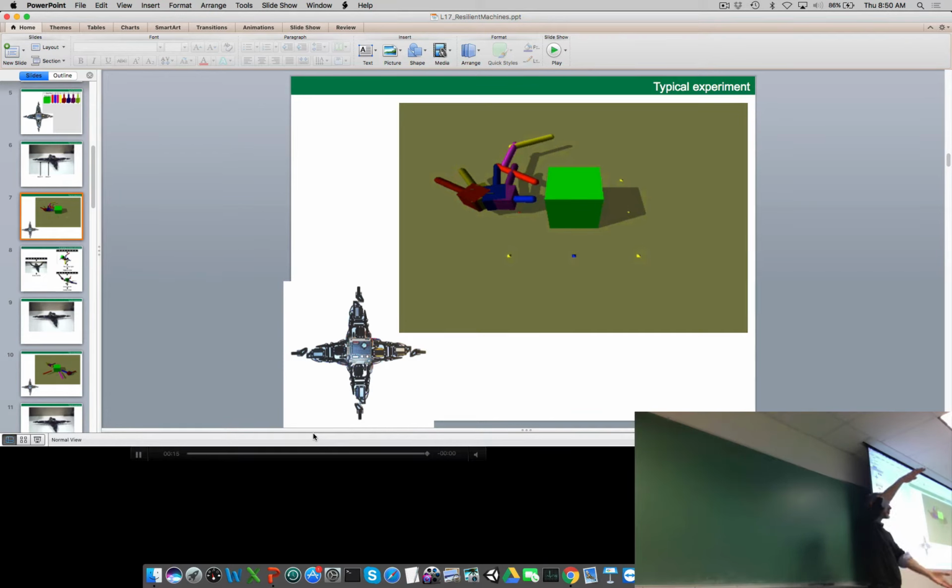This third evolutionary algorithm also has a population of controllers. We take each controller in that third population, plug that controller into each of the 20 virtual robots. What is the fitness of that controller in this third evolutionary algorithm? What are we looking for? What kind of controller are we looking for in this third evolutionary algorithm? One that gives you a variety of predictions. One that gives you a variety of predictions, exactly.